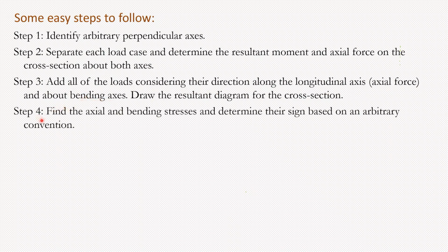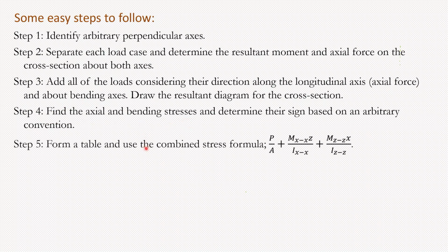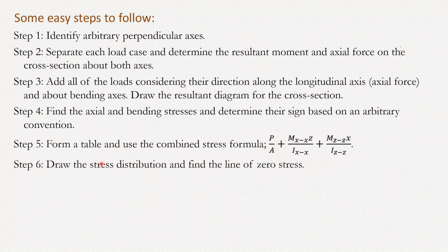And then we're going to find the axial and bending stresses based on the formulas we know. For example, the axial stress formula is just force divided by area. And for flexural stresses, again, My over I, the famous formula that we have for flexural stress. And then we're going to find these stresses and combine them together after finding them, right? So you have the axial, you have the flexural, and so forth. And at the end, we're just going to draw the stress distribution, which is just a schematic, a presentation of how everything looks on a cross section.